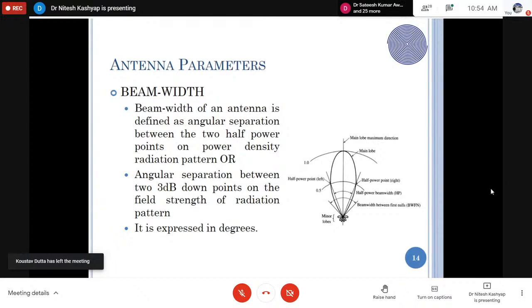So we can evaluate or find the distance of the antenna where we can place the receiver antenna after the measurement of the far field or the radiation pattern, where the antenna is actually radiating. So the beam width is a key characteristic of the radiation pattern here.